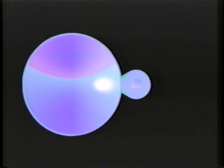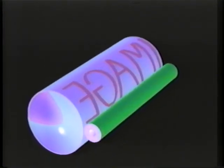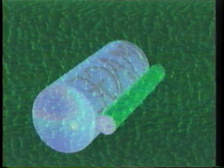As the photoconductor drum rotates, the latent image approaches the development roller. The roller's surface is coated with developer, a mix of toner and carrier. The toner carries a charge opposite that of the latent image. For our example, the latent image is positive, so the toner is negative, shown in green.